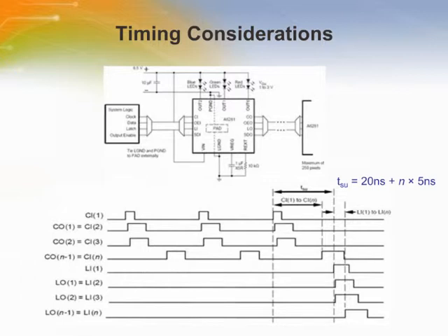These LED drivers can be used in large numbers to drive many LEDs with control signals connected together serially using short cables between each pixel, as shown in the diagram. Because the negative edge of the clock drives the data to the serial data output pin, and the clock output pin is driven by a 100 nanosecond one-shot function, the clock and data signals remain synchronized from the first pixel in the chain to the last.